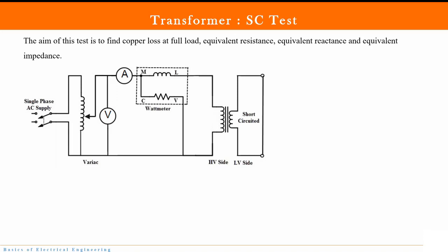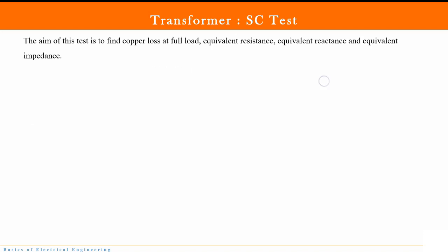Okay. Yes. So when I draw the equivalent circuit here, I neglect all the components, because core loss is negligible. So I can very well neglect R naught and X naught, so that whole branch is neglected. Remember, we had already drawn the smallest equivalent circuit when we were studying the equivalent circuit.